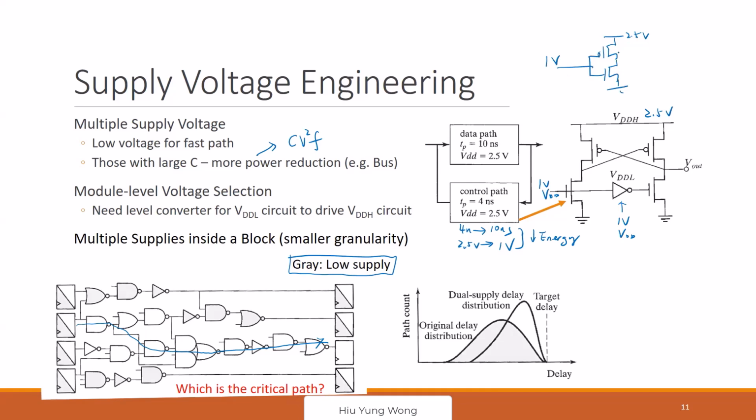You cannot turn this off, right? You turn this on, but you cannot turn PMOS off. Although your input logic is 1, you expect the output to be 0, but you cannot turn this off. This cannot be 0, right? So what will you do? You will use this type of couple logic.